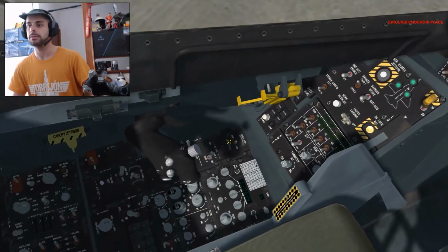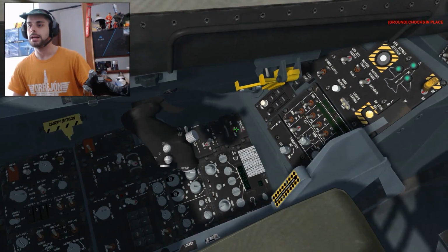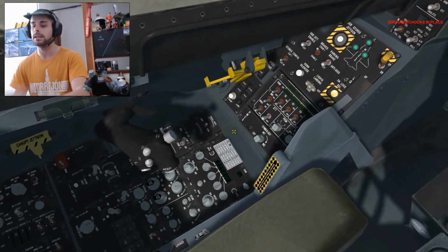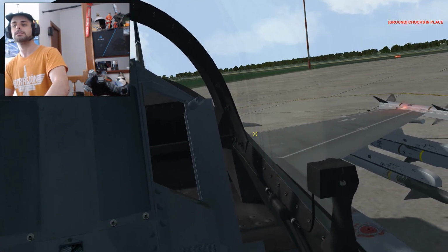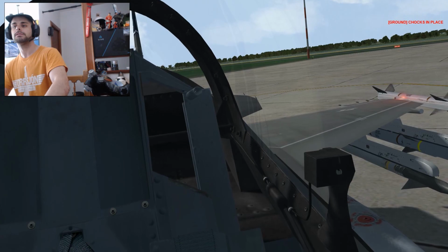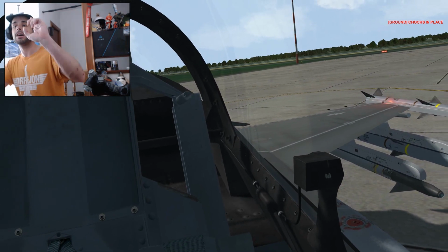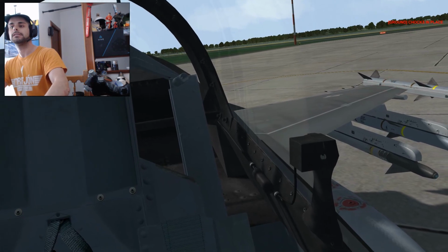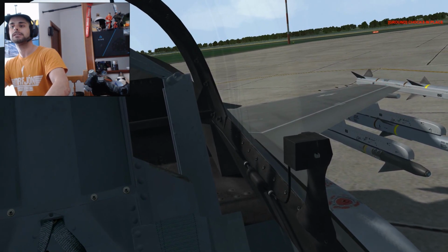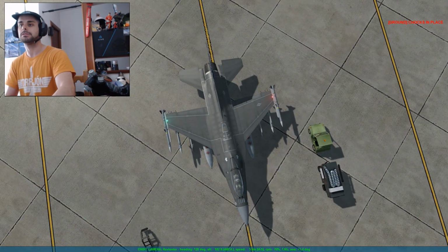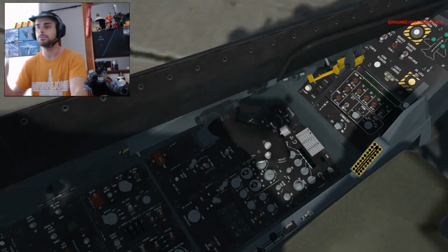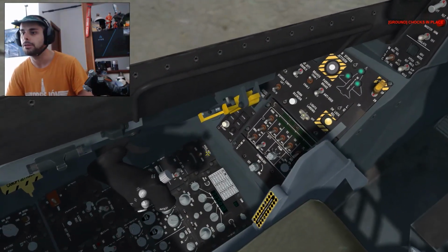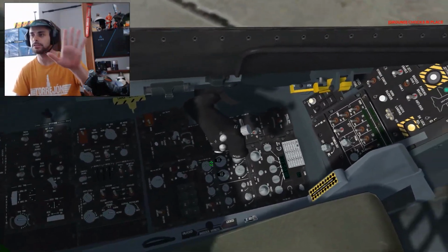Another test that you can perform is this manual pitch override, but I recommend you use the O key on your keyboard, because I am looking to the left. Look at this, up position and down position. Okay, it's working. Now I'm going to press the O key. As you can see, there is movement. Again, press, and now in external views, it's going to be easy for you to see. Press, press, press, press. This test is to be sure the manual pitch override is working. Okay, left console is done.